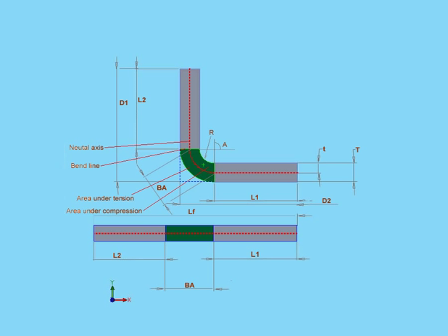There's not really a scientific method or formula for determining a truly exact calculation of the bend allowance, and that's because there's so many factors at play during the production of your sheet metal part. For example, actual material thickness, an infinite variety of tooling conditions, forming methods, on and on and on. There are many variables here, and in reality, many methods are used to calculate bend allowance. Trial and error is probably the most popular one.